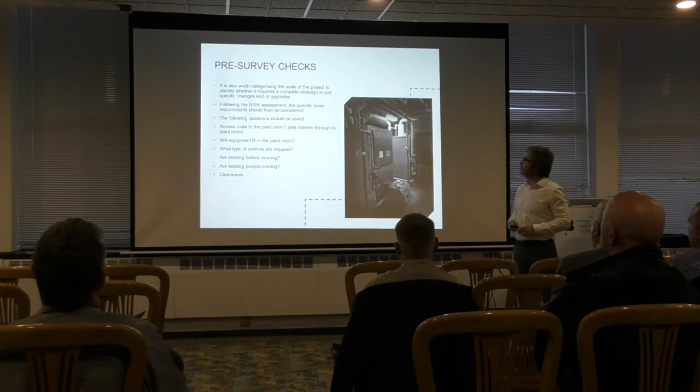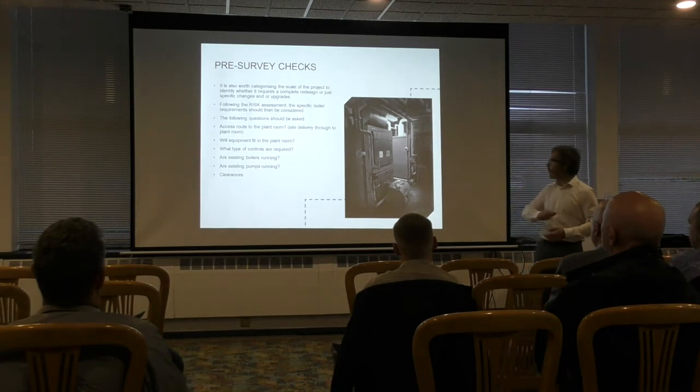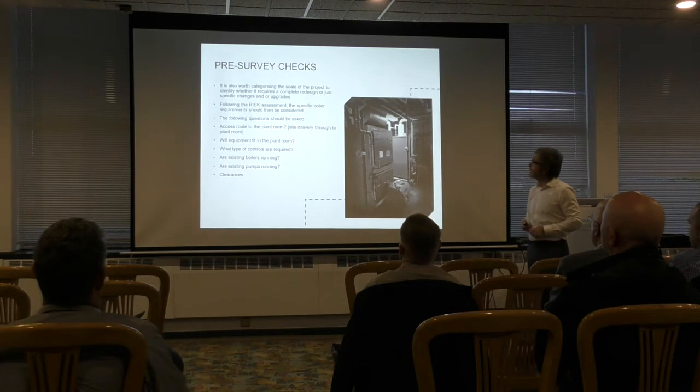First up, categorising the scale of the project. So, are we just looking at the client just wants you to replace those boilers over there? I'm not interested in replacing anything else, just get the boilers replaced. Or are we looking at stripping the whole plant room out and starting again? So that's just categorising what we're actually looking at.